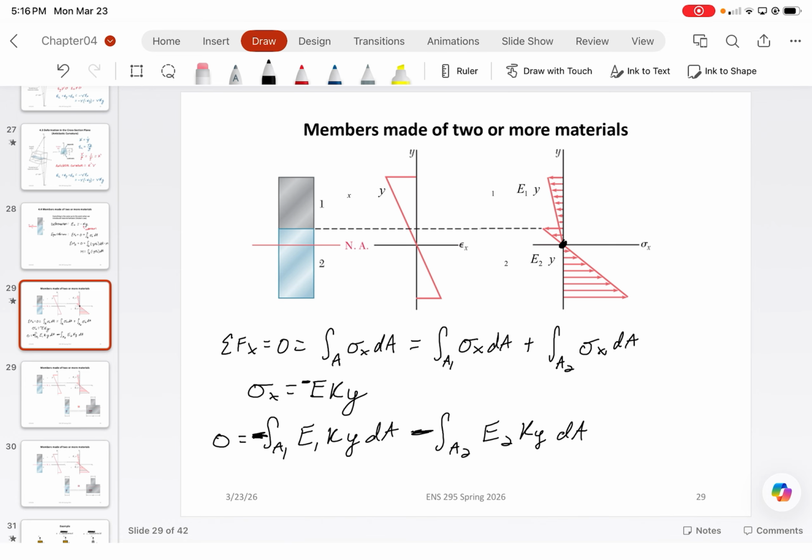All right. Now, there's one problem with this, and it's two unknowns, right? We still have too many issues to deal with. So one of the ways that we really solve this is through a transformation. When we were dealing with composites previously, we were dealing with it indirectly through a ratio of the elastic moduli.